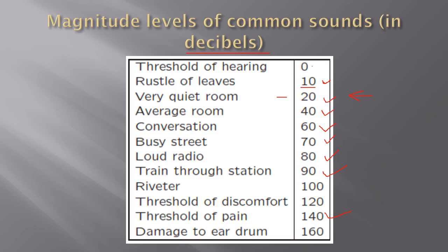When our system is turned on, our system will receive a signal with the strength of 20 dB, and that is only noise. So we would like to neglect those signals. We are not interested in a signal of power 20 dB or below.